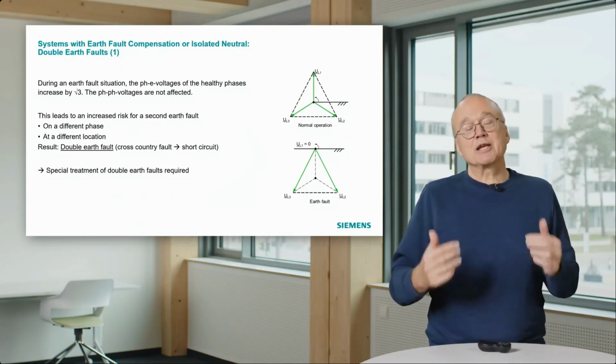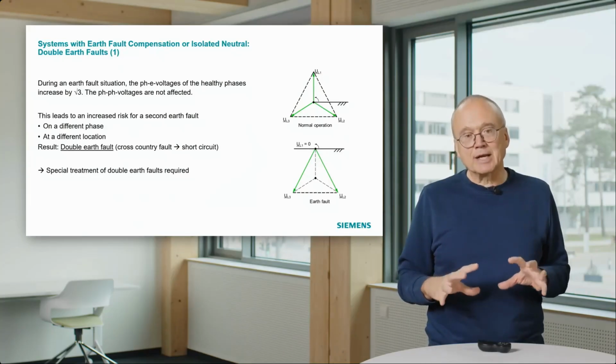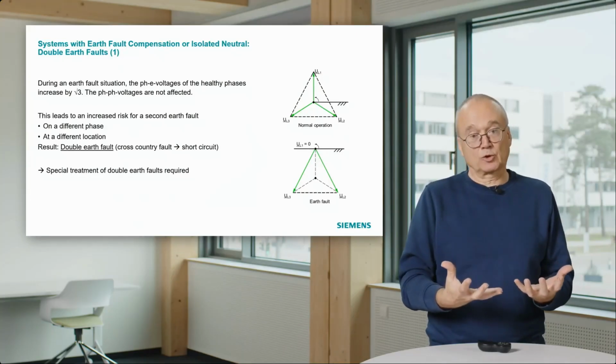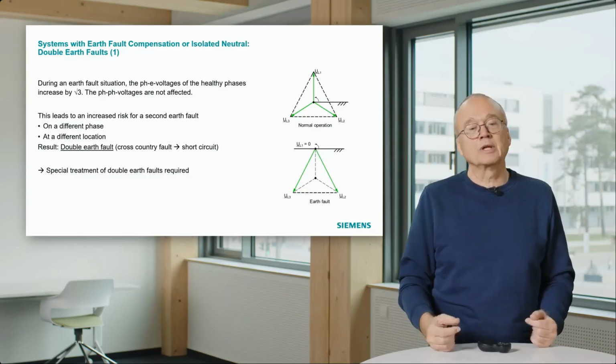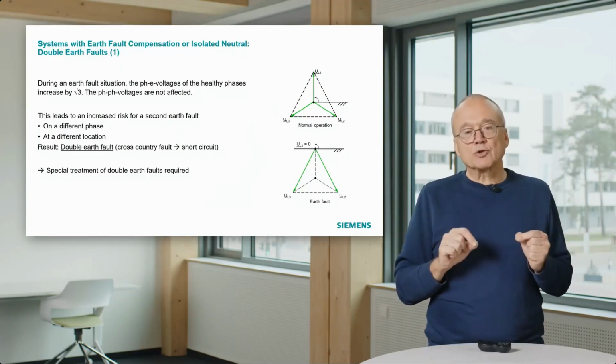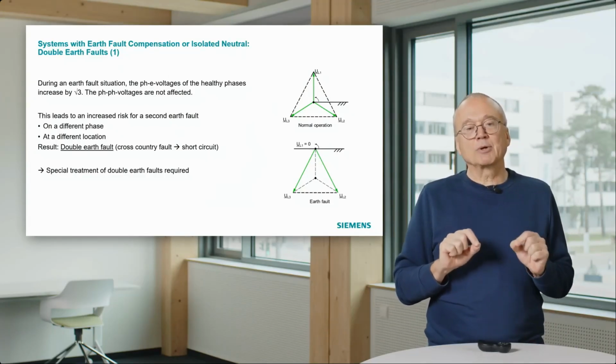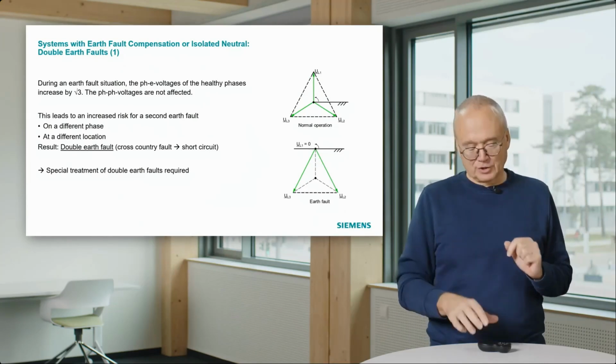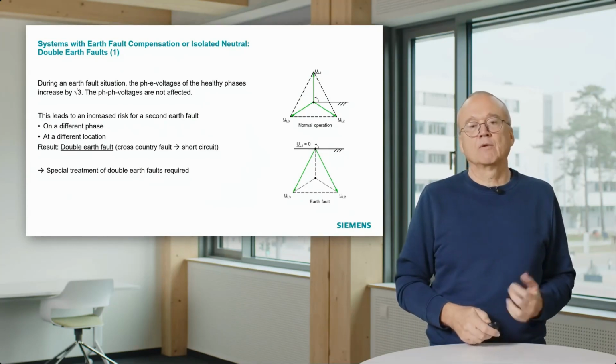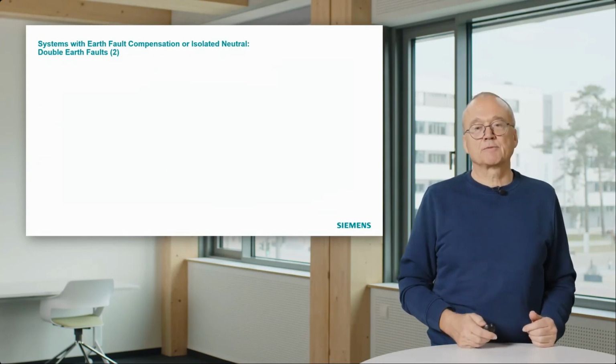And that means if you apply a distance relay in such a system with earth fault compensation or isolated neutral, you need a special treatment for these double earth faults or cross-country faults. Why do we need a special treatment?